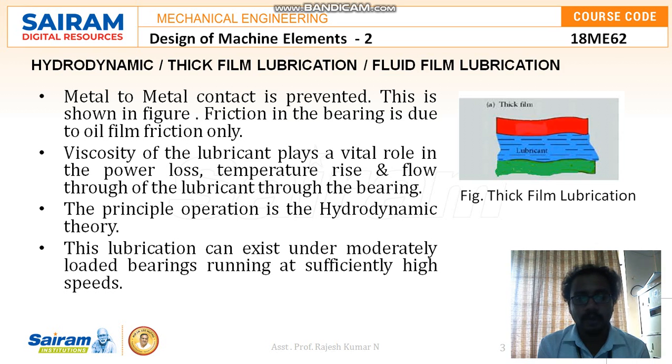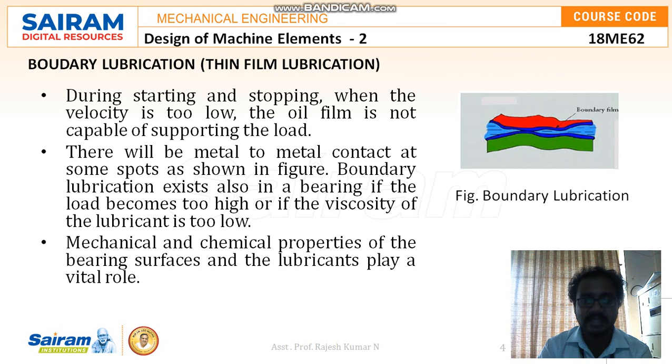The viscosity of the lubricant plays a vital role in the power loss, temperature rise and even the flow of lubricant throughout the bearings. The principal operation is the hydrodynamic theory. This lubrication can exist under moderately loaded bearings running at sufficiently high speeds.